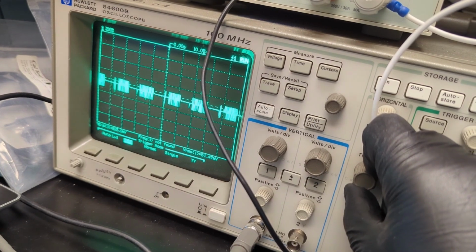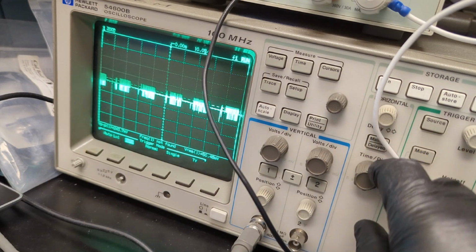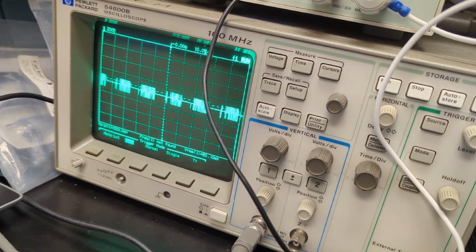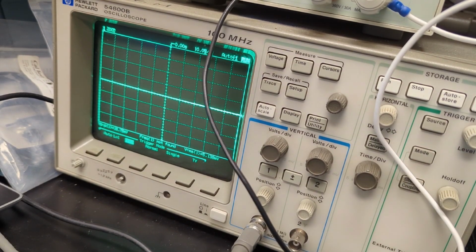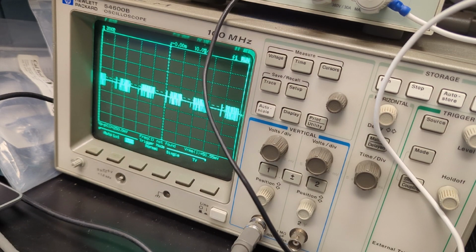That's on pin 13 of U435. So there's definitely something going wrong there. Now, if we probe each of the other ones, as an example, this is U436. And that's U437. So it seems to me something must be wrong with U435.